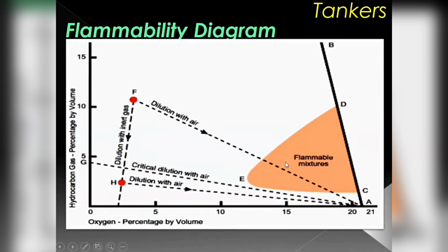Now the tank is sealed. Why will the explosion take place? Anyone? Maybe because of heat. No. When you're doing the tank cleaning, you're disturbing the sludge. You are generating static current that will act as a spark. Now all three sides of the triangle are available in the tank. A beautiful atmosphere to have an explosion. You have a fire, and then after that you have an explosion.